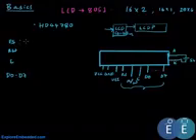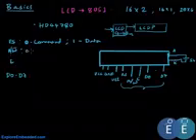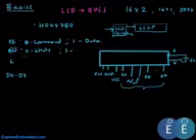Now register select, when it is 0, selects the command register inside the HD44780 graphics controller. When it is 1, it selects the data register. We can write this as read/write bar, to understand it better. When read/write bar is 0, commands or data are written into the LCD. When it is 1, we read from the LCD, so we read either command or data.